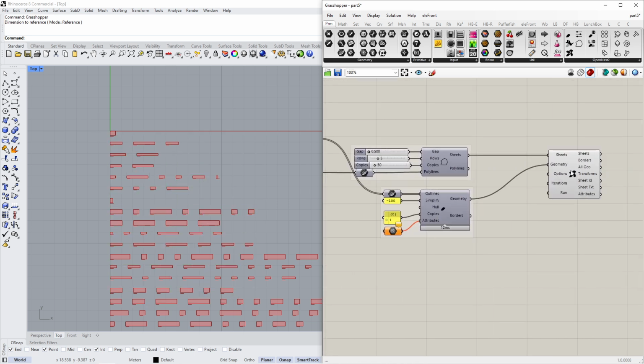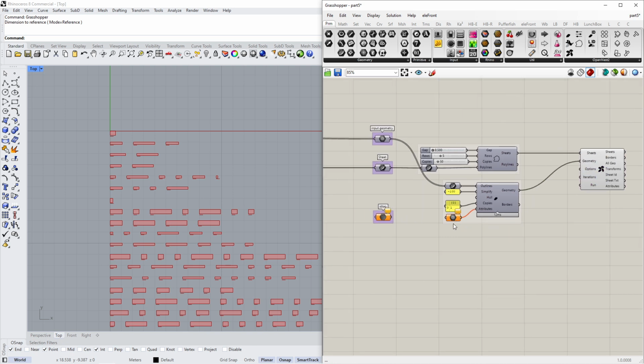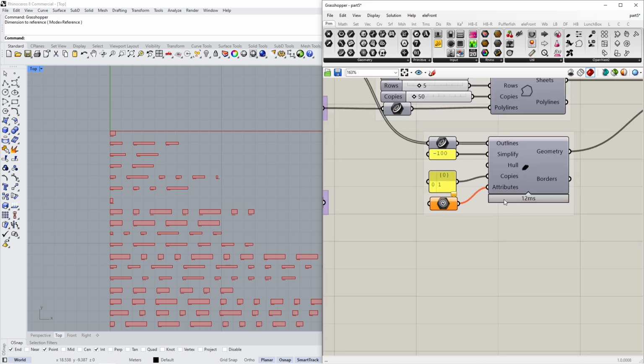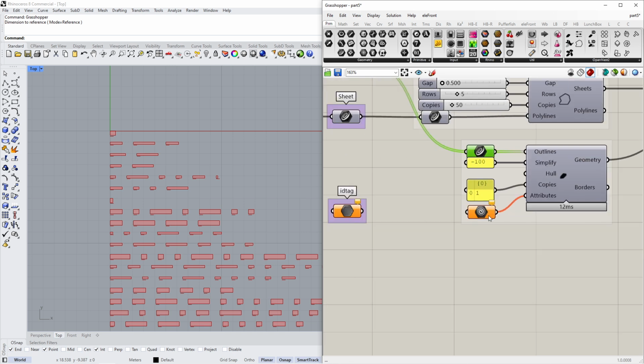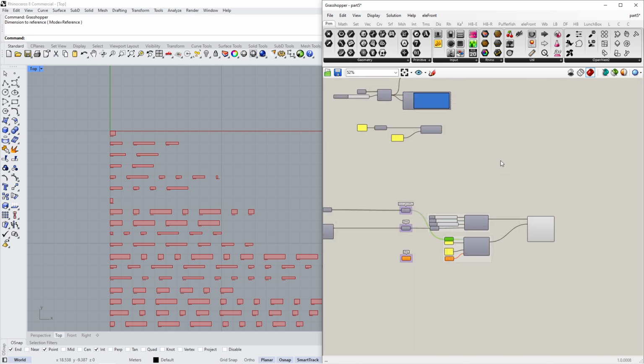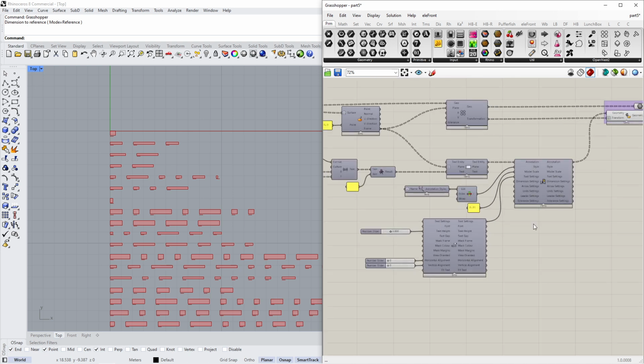And then the last thing I want to do before running this component is add its attribute as well, which we can do here. So besides the geometry for nesting, we can also include attributes, which can be anything. It can be accompanying geometry. It can be like an ID tag, which is the one we're going to include, but much more. So for that, we have to set up a text element like we did before.